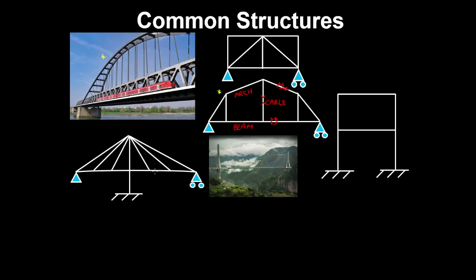Now the cable-stayed bridge also consists of a beam which develops bending loads, and the cables also support the beam through tensile loads, and the tower can be modelled as a column which takes compression loads, and these loads are ultimately transferred to the supports or the foundation.